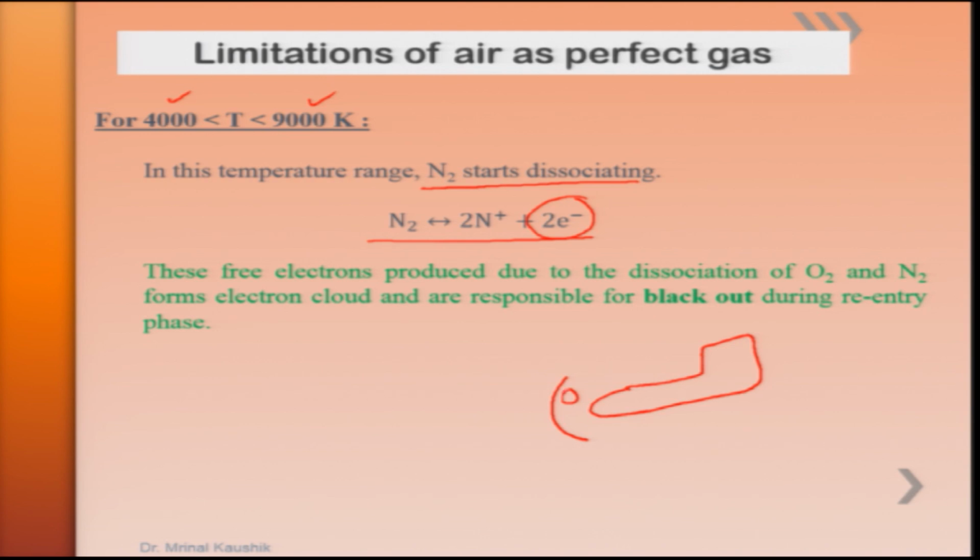That means the temperature here, taking the dissociation effect into account, is approximately 9200 Kelvin or so. Under this, a sufficient number of free electrons forming the electron cloud is present in this zone, which disrupts the signals from the cockpit of the space shuttle to the ground relay center. And it takes around 15 to 20 minutes in which the ground control unit does not have information about the space shuttle, and that is essentially what happened with the Columbia space shuttle.